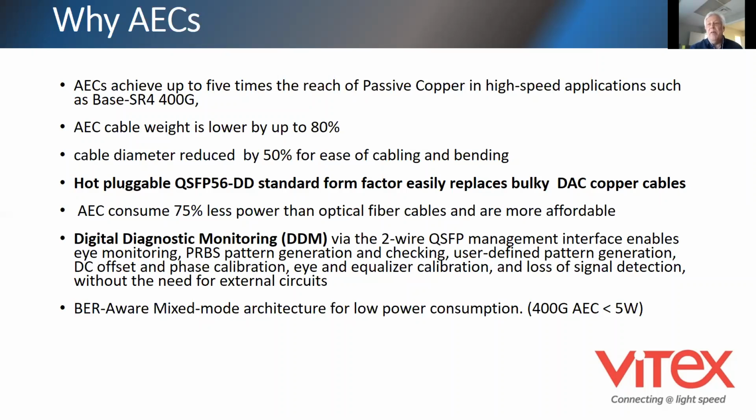Some of the things that we get with this direct attached active copper cable are 4 nanoseconds latencies, BERs of 1E minus 15, and low power consumption, basically less than 5 watts per end, even at the 400 gigabit bandwidth level.